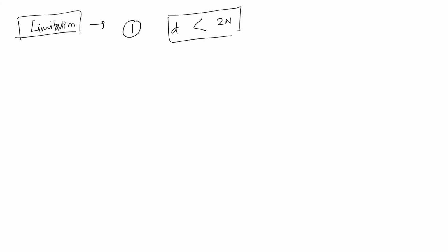And now we talk about the limitation. This is a very important thing in the plate load test. Number 1, this test is only valid if depth is less than twice width. Otherwise, if it is greater than that, then this test is not valid. That means probably in shallow foundation you go with this test. For deep foundation or higher depth, you don't apply this test.